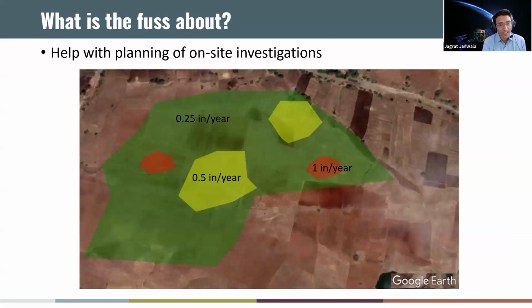So I have used InSAR for planning of on-site investigations. This is especially useful if the proposed construction site is a stabilized mine site or landfill. The typical approach is, within the building footprint or structure footprint, get as many borings or CPTs as possible and use that information to design your job.